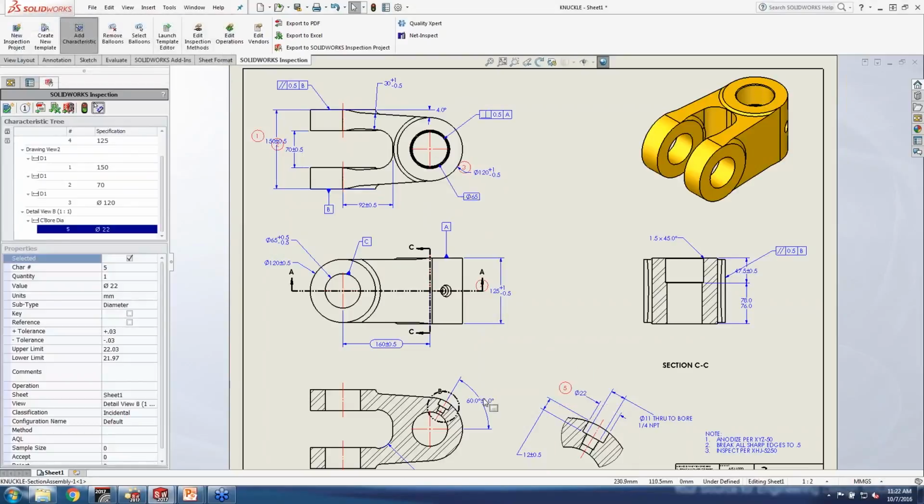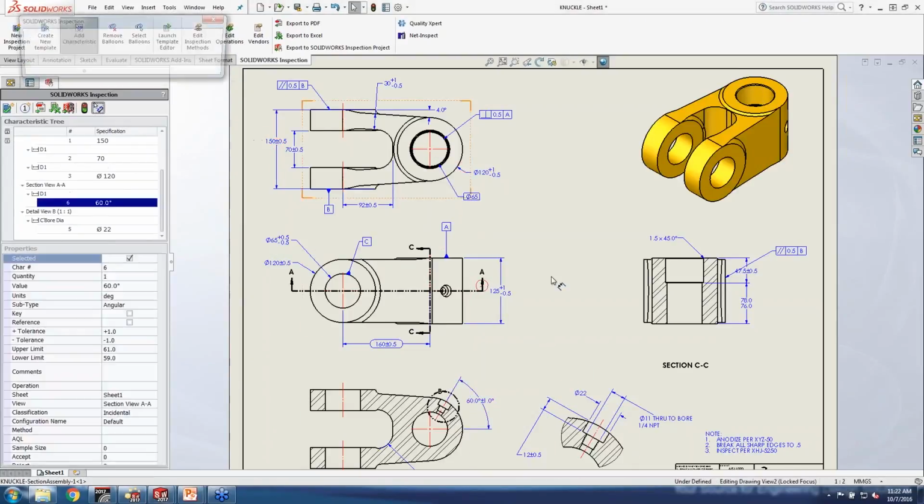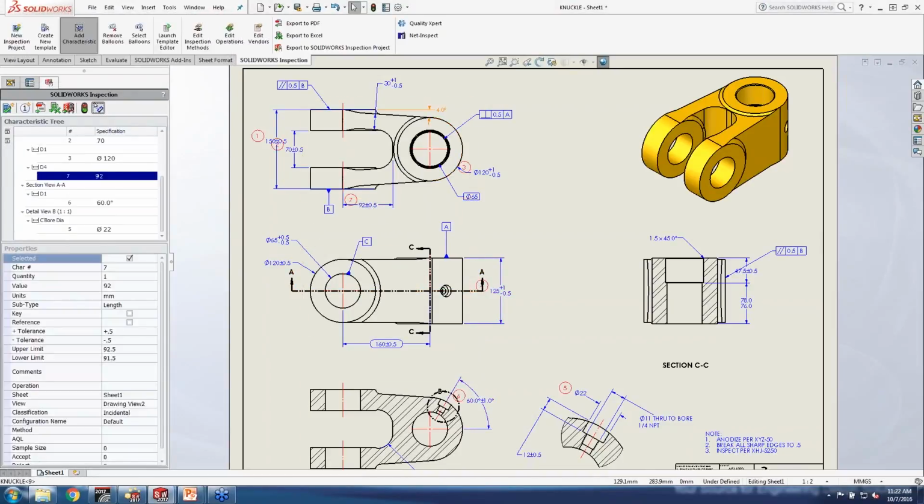And when you start selecting components, SolidWorks Inspection is not always going to put those balloons where you want them. Sometimes they're overlapping items. I hear a lot is like, oh, you know, I want that fixed, and you can control where they're placed in the options. But really, typically, there's no good place that works for every single selection. So just select them. They'll put them where they go. You can always move them later, which I'll show here. It's not a big deal.